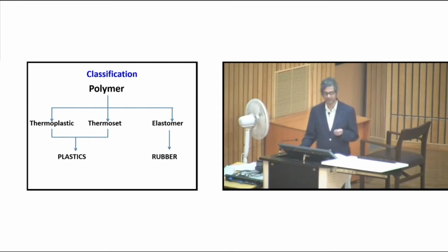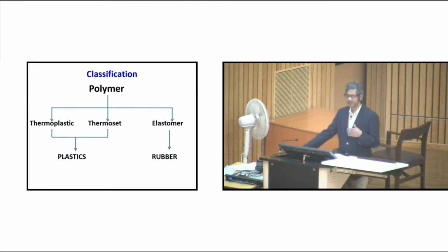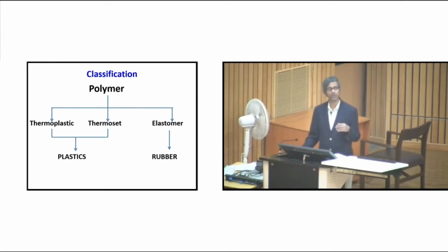That is why they are called thermoplastics. As you raise the temperature, they will melt, and again they can then form the plastics. But thermosets are like bakelite, which once you set, you cannot get it back. So this is basically the problem of polymeric material. Most of the polymeric materials, hence thermoplastic materials, are more widely used than thermosets. Elastomers, you all know from the literature, are basically rubber bands, and even tires are also elastomers. They are widely used in the materials community.